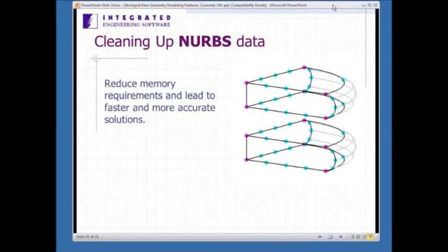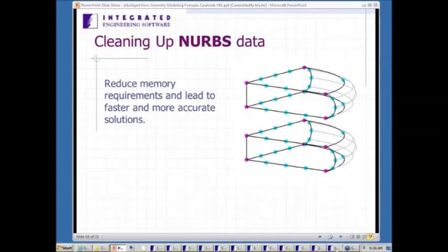During the course of the field solution, we have to calculate derivatives. If we can do that analytically, as we can on a line segment or an arc, that reduces time and it's also more accurate. So here I've deliberately constructed a model where I broke up the segments and some of the arcs into several sections and then deleted them and made freeform curves such as NURBS. So I'll show you how that works.